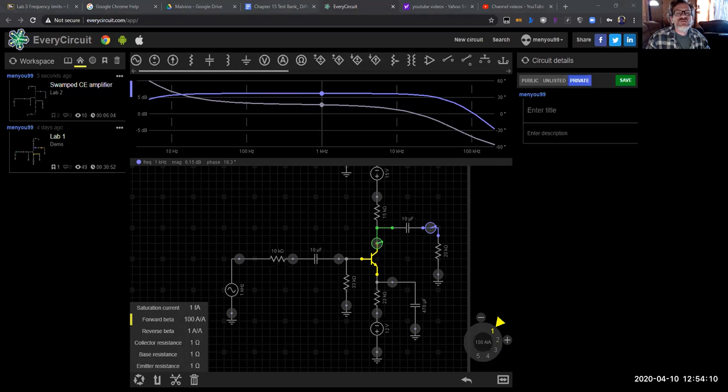So I didn't think it was that bad as far as being able to look at it. You basically change C1 to 10 nanofarad and C2 to 10 nanofarad and see what the overall effect is. Don't worry so much what the percent of deviation is. And essentially, what are we looking at, right? What effect could resistor and capacitor have on critical frequencies? Well, once you go through the whole lab, you can see how that changes things, right?